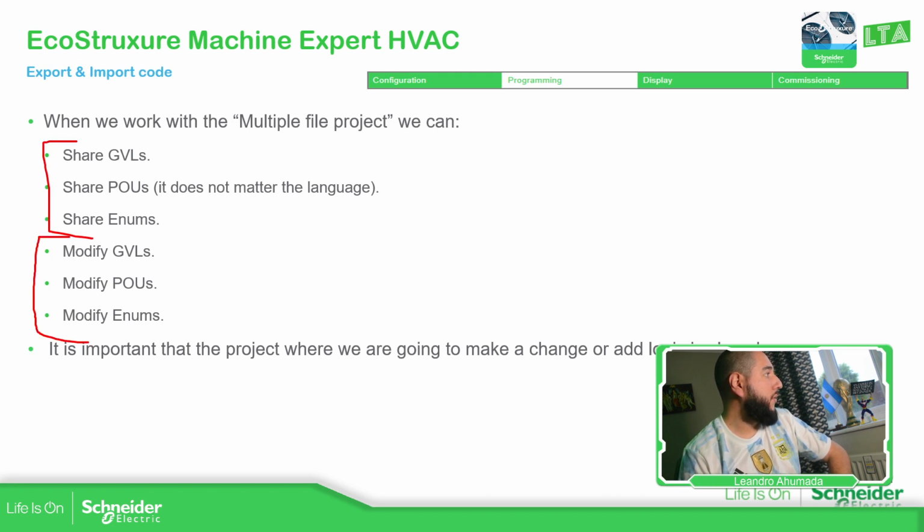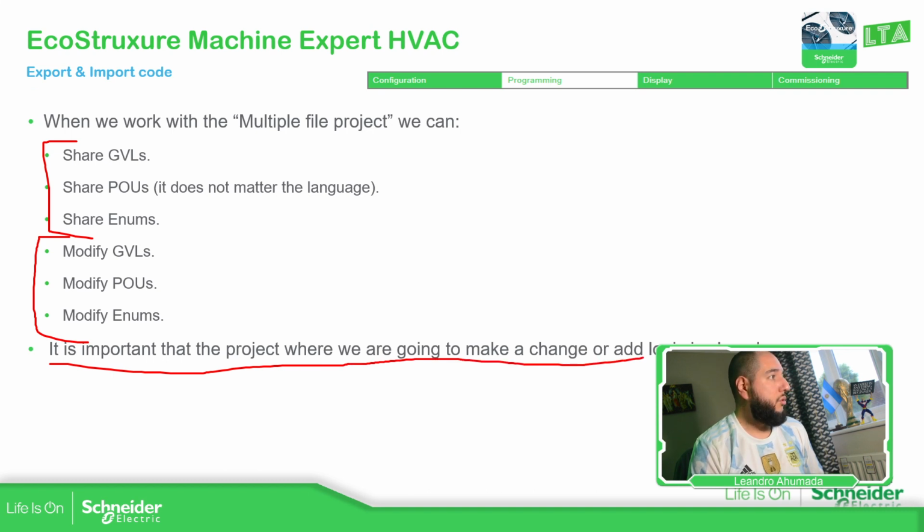Okay, and we should be able to modify it if we want, from one to the other. Of course, it's easy to make modifications, for example, when we're using structured text, but if you're trying to use FBD and ladder, you need to be cautious. It's not straightforward to make modifications because they have some specific identification for each rung and for variables. The best would be to import it and then just manually change it in the software, not in the file.